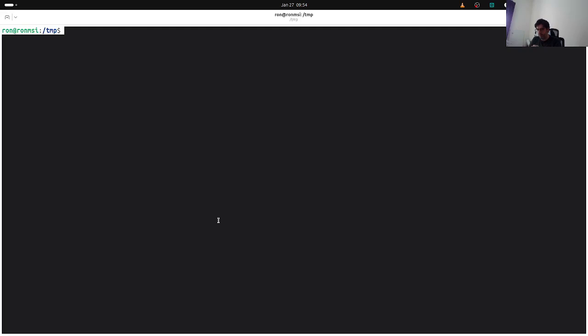We say, okay, we treat the device as if it were pristine, and I show you the techniques by erasing the eMMC, at least the blocks that the boot ROM would be looking for, to get the bootloader chain, the trusted firmware, and then the U-Boot. I show you the techniques to have the device as a pristine device and work with that. So I hope this is useful. It's very useful if you work with these devices and try to modify things.